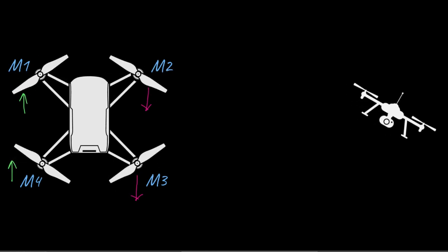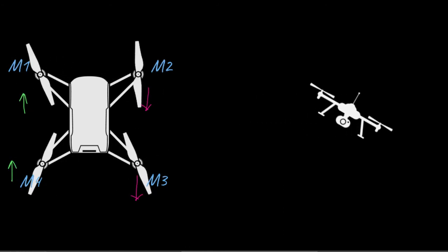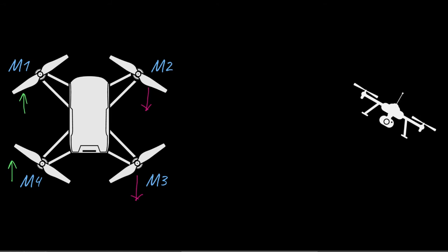This is necessary because a quadcopter has 4 inputs, but it can have 6 ways of moving. And because there are more outputs than there are inputs to control it, you generally consider this quadcopter an under-actuated system, which means for every motor configuration, there is not one that directly relates to, say, a particular translational output, in this particular case, moving right. So in order to move right, the quadcopter needs to first tilt, and because of the tilting action, it then moves towards the right. This is how you can control the quadcopter for it to move in different directions.